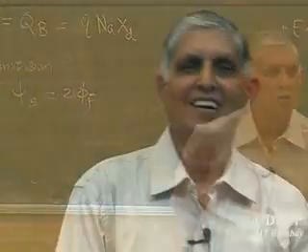Anyone? We say EI is bending towards EF because you want hole concentration to go down. You can see from here more and more holes going down means the depletion layer enhances. So as holes move down, P is equal to Ni e to the power EI minus EF by KT. The Boltzmann relation says EI must come closer to EF. As EI becomes EF, P is Ni.